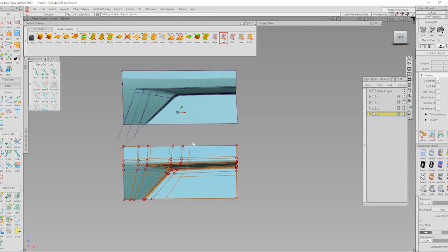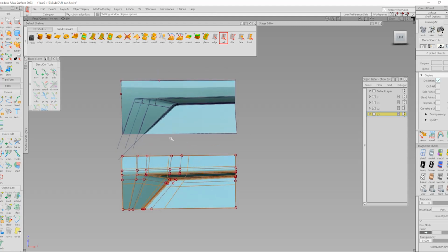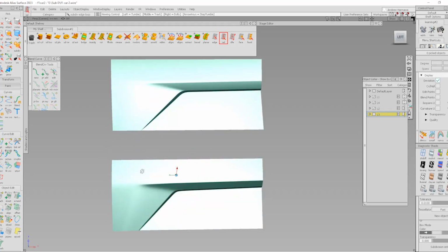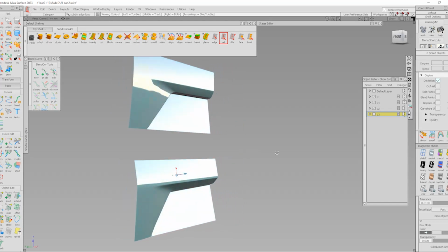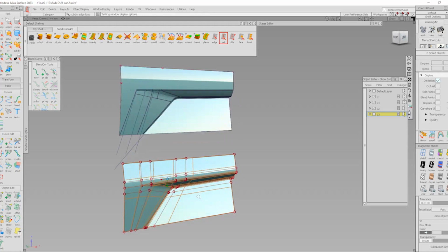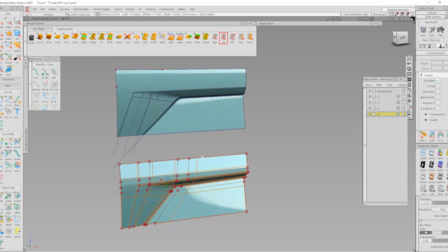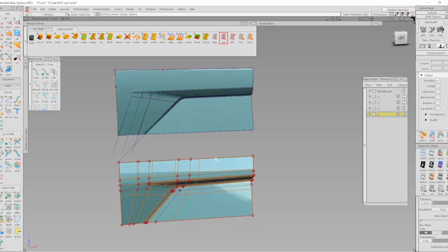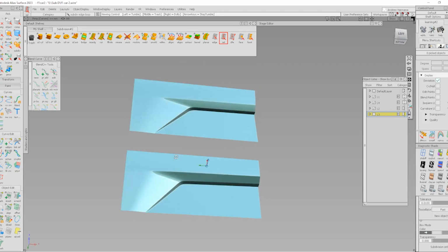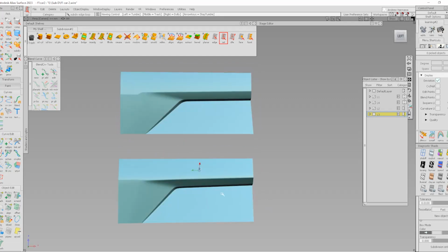Same shape, but two different methods. One with SubD, in my opinion, it took way less time, and it's not just about taking less time. It's about having it being very friendly to use, with using just pushing and pulling CVs instead of in Nurbs you use curves. And then from using curves, then you project them and you monorail them. And then you still have to trim and then blend.